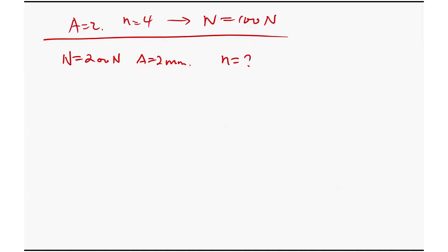But let's see how you solve it. How do you find the safety factor? That's basically the question. What's the safety factor? It's the yield stress versus the allowable stress, or your working stress. What's the yield stress first? The same material, so yield stress should still be 200 megapascal.